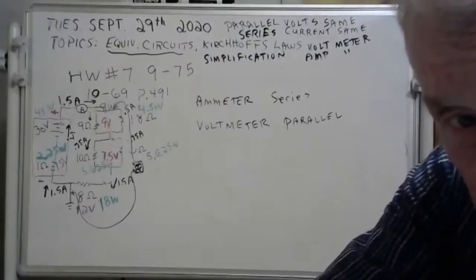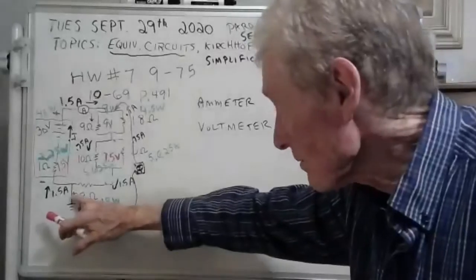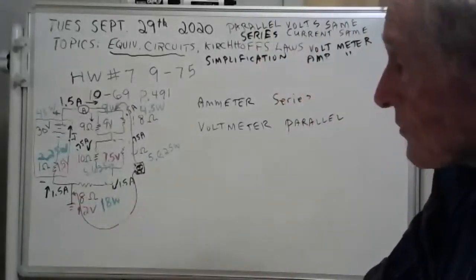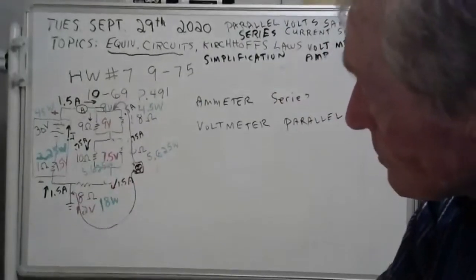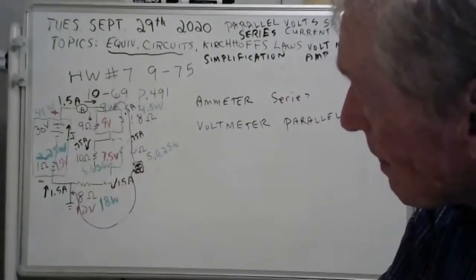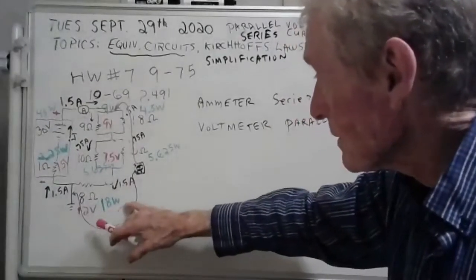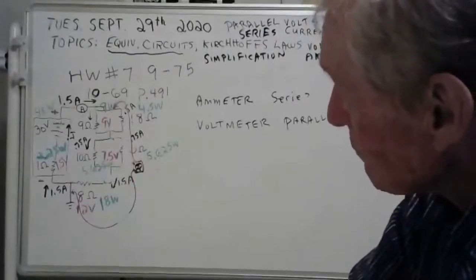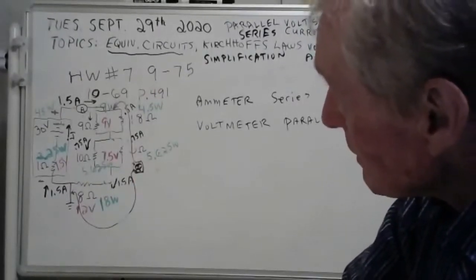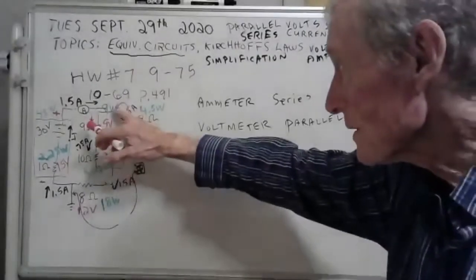We'll pick on Zach. Zach, if you put your black lead here, I got 28.5. What do you get for your volts there, Zach? 28.5. Now let me do it. You have 12, 7.5 makes 19.5. Another 9, 28.5. Good going, Zach. You would measure 28.5 there.